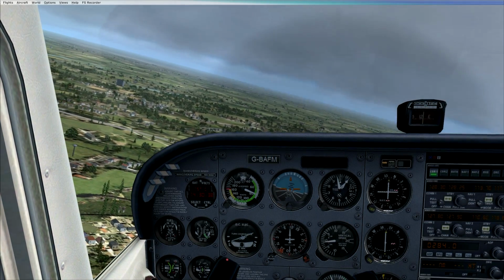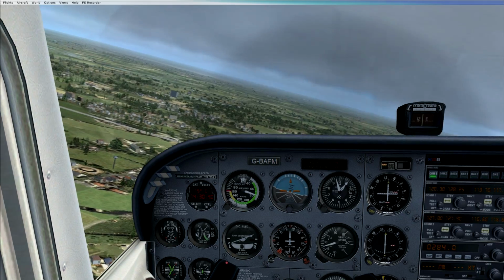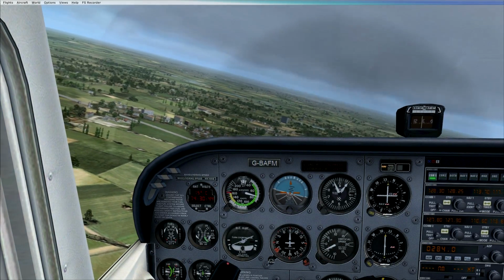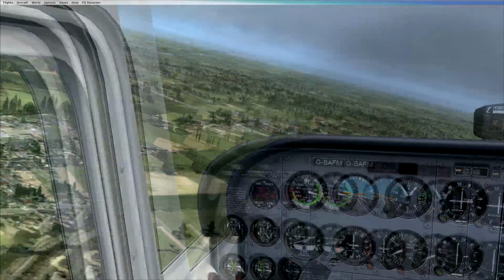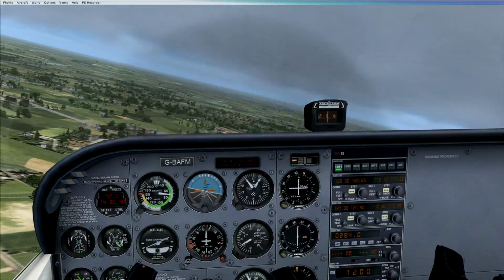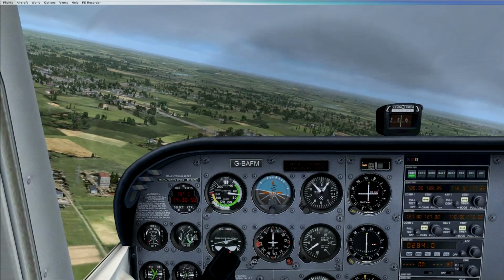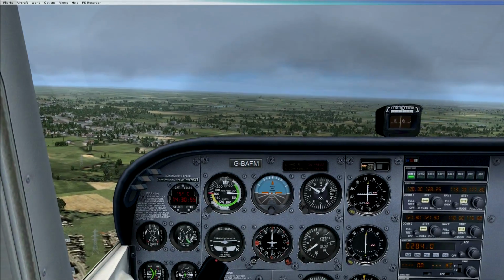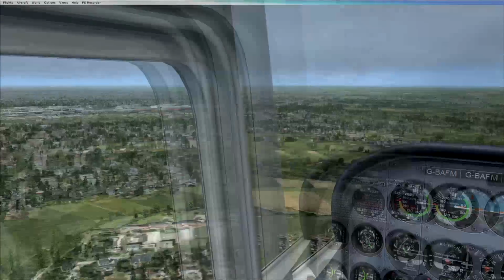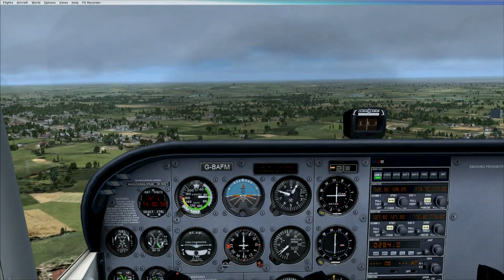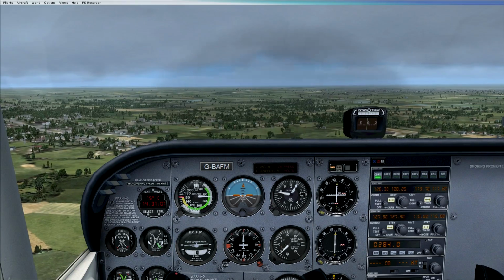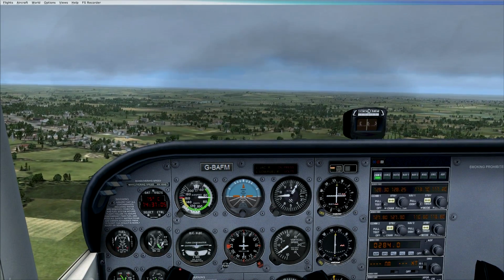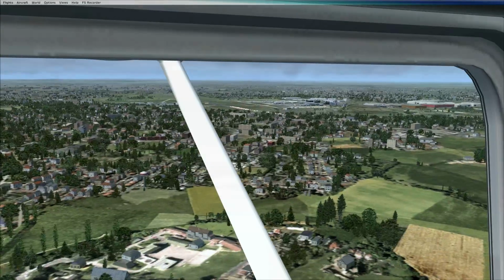It's just started to rain in Birmingham, so it's deep joy, lovely for us. We're into the white arc of the airspeed indicator, so we can put our first stage of flap down as we continue to slow down. Now because of high wing I can't see where the airfield is, which is why it becomes useful to have our markers. So I've started turning so that we're onto 060, and you can see we're nicely perpendicular to our runway now. Now the speed's 70 knots, which is fine at the minute because we've only got one stage of flap down. Try and trim us out a little bit.